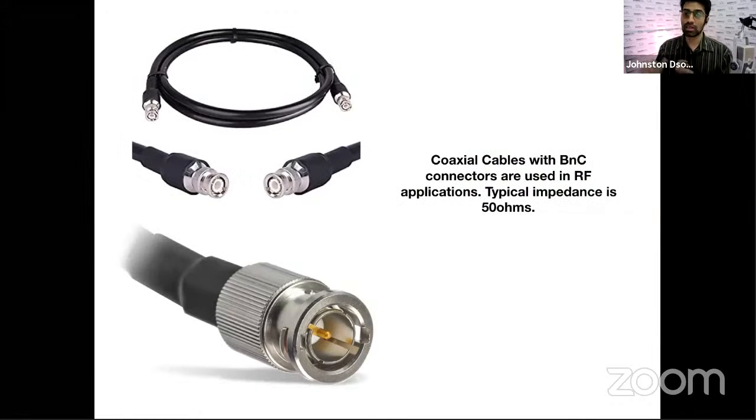Secondly, we use coaxial cables with BNC connectors in RF. Okay. Now, coaxial cables with BNC connectors are used by the video guys as well. So you need to be very sure about which cable you're picking up for your use. We use a 50 ohm cable. The video guys will use 75 ohm cables.